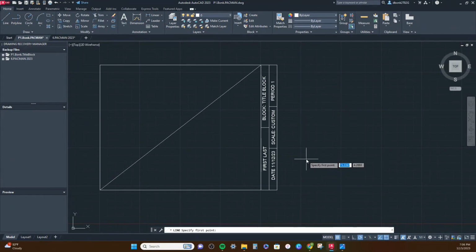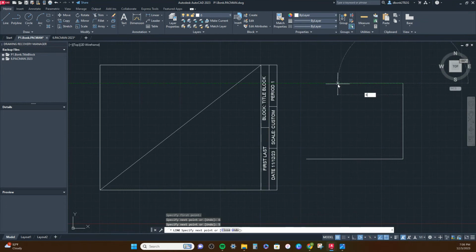I'm going to draw a 6 inch by 5 inch box, which I'll do. Start to the right, 6 inches, hit enter, go vertically, get a green dotted line, write the number 5, enter, back to the left, 6, enter. Click to connect and make sure you're careful and hit the escape key to finish that step.